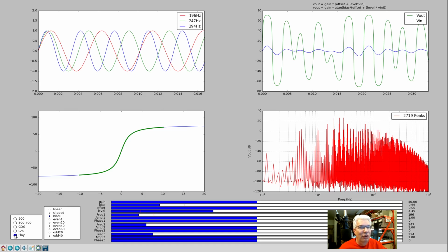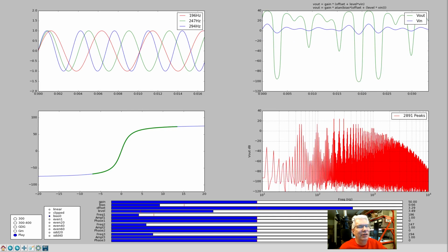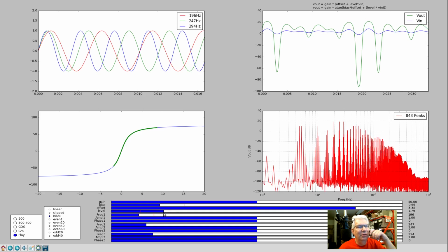Now that might be the tone you want. I don't know. We can change also the characteristic of this by shifting the waveform up here, and this is the whole point of this investigation, was if you're designing with a Pentode, what screen voltage do you pick, and where on the curve do you want to actually have your input riding, because you do get to create based on your choice of offset, do get to tailor the output so that you get predominantly second order harmonics.